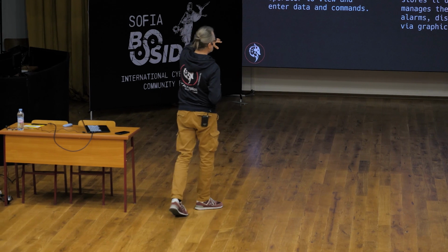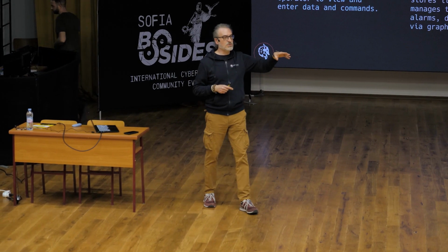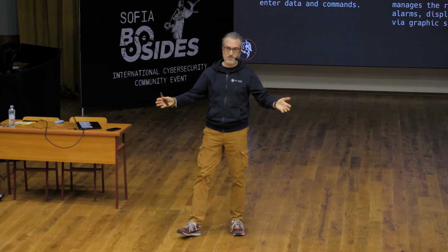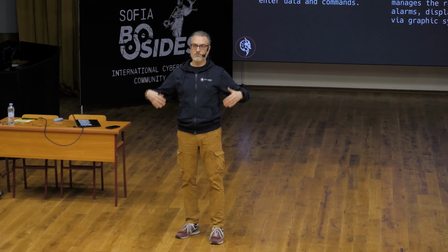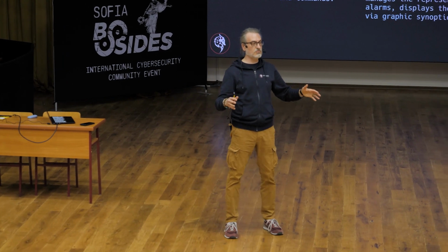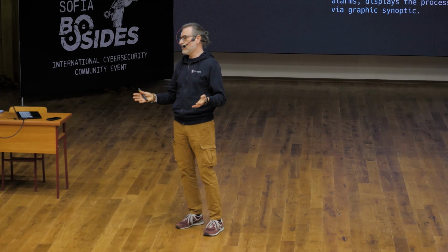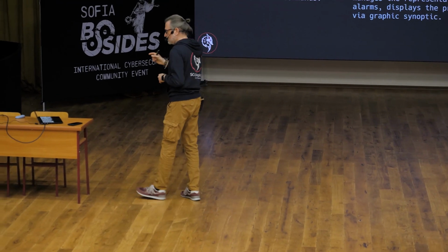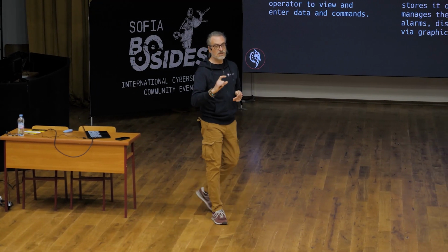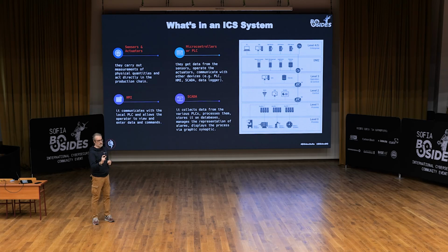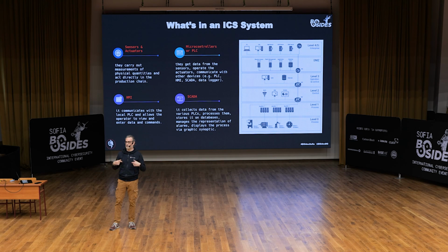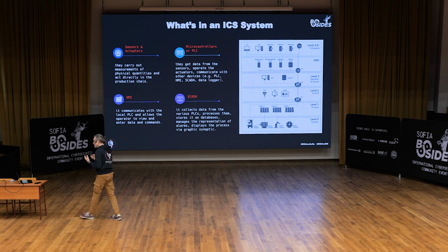And then we have a SCADA system. SCADA on level 3 is supervisory control and data acquisition. It's software that runs inside a PC, a Windows PC in most cases, and collects all information coming from different PLCs using specific industrial control protocols. Industrial protocols means Modbus TCP, Profinet, DeviceNet, OPC UA, CANopen, and other specific protocols. Consider that in industrial control systems, we have more than 150 proprietary protocols. It depends on the vendor; they are produced and defined by the vendors. We have some standard protocols like Profinet, Modbus, but some protocols are defined by a specific vendor for their equipment.